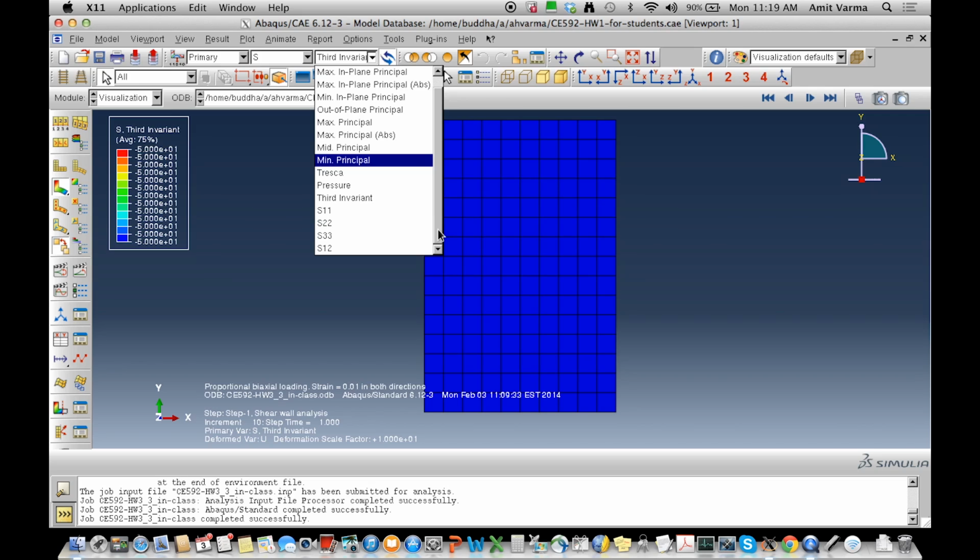All right. So the pressure is going to be, I really want to be able to see, yeah, these were the Prandtl-Reuss relations. And S11 and S22 were equal to sigma 11 minus sigma m and sigma 22 minus sigma m. It so happened that for the proportional loading case, sigma 11 and sigma 22 are equal. Sigma m is also equal, which means S11 and S22 are equal. It's really proportional loading, and therefore d epsilon 1 P and d epsilon 2 P are equal. So when I integrate it all, I get the same plastic strain whether I'm looking at the 1,1 or the 2,2 dimension.